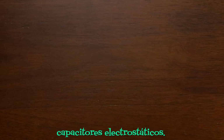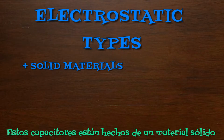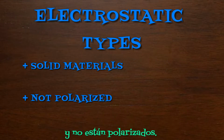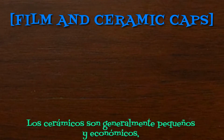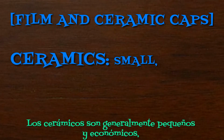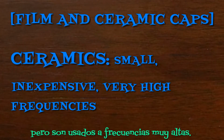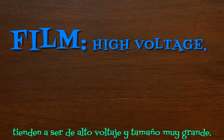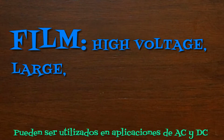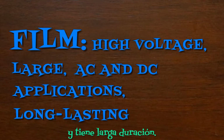Group number 2, electrostatic capacitors. These capacitors are made out of solid materials and are not polarized. You'll find your film and ceramic caps here. Ceramics are typically very small and inexpensive, like electrolytics, but are used at very high frequencies. Film capacitors, on the other hand, tend to be high voltage and very large in size. They can be used in both AC and DC applications and last a long time.